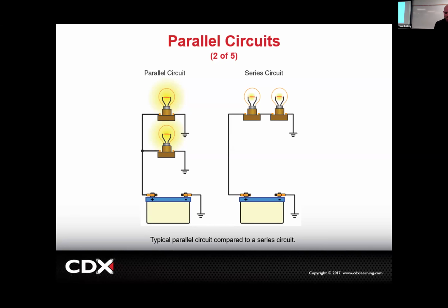So if a truck driver says, hey, I got my cool truck and I want to add a bunch of lights, and they just start adding branches on branches on branches, the original feed down here is now supporting many, many more bulbs. So you may have a lot of amp flow down here, maybe too much for these wires. You just need to get a bigger wire just for that section. Yeah. It's kind of like, I mean, our local and state governments are guilty of this.